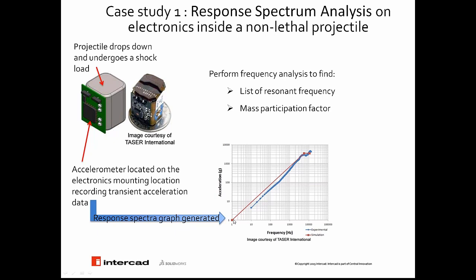We estimate the first section as 1 to 2 here, which is the first step of acceleration versus frequency, and we simply estimated the second section of the curve by 0.1 and 0.2 as a linear line. That might be close enough as curve fitting to the experimental data, but definitely you can enter the rest of the data if there is any significant variation in frequency and acceleration.